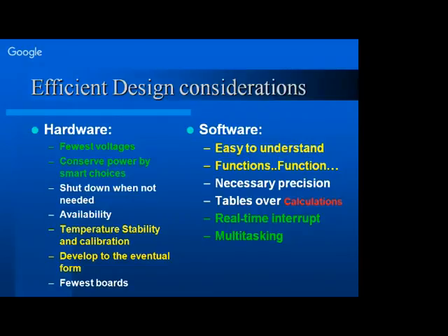So in case of embedded system also, what you should be doing is that you should not be keeping your CPU busy. So let's say you have some application wherein a lot of calculations are required. One of my recent PhD scholars is developing some algorithms for extracting the sine wave correlation fitting components out of that impedance vector. So I asked him, instead of keeping the CPU busy, you do everything offline. Okay, you develop this algorithm on the desktop PC first, find out the components, find out the best algorithm, best fit function, and then finally program those regression coefficients along with those design variables inside the core controller. So this is how we can do.